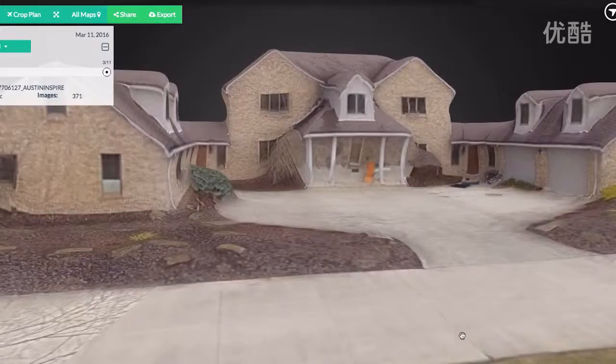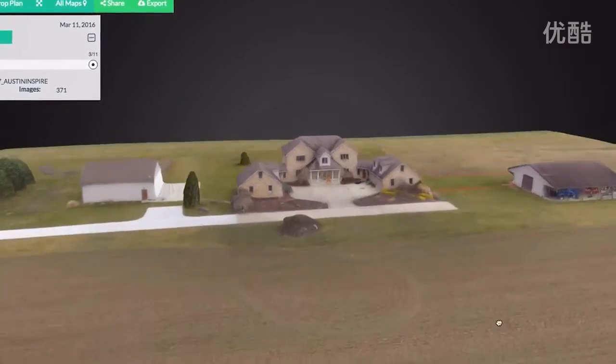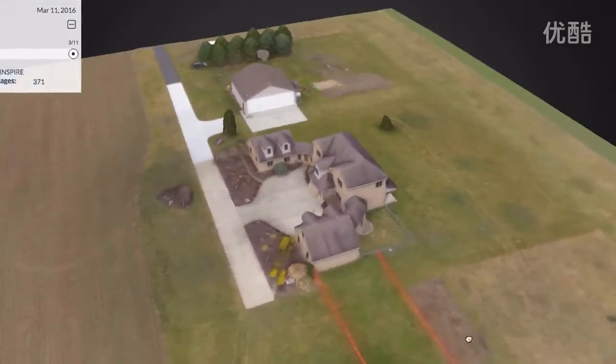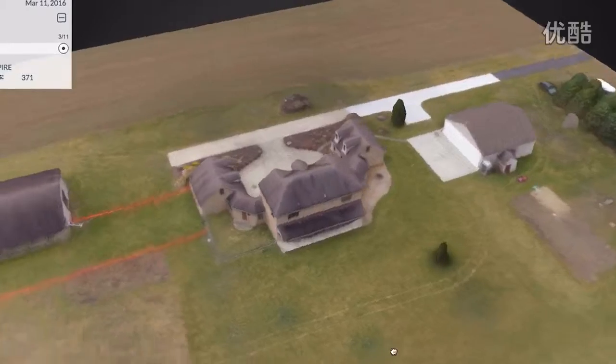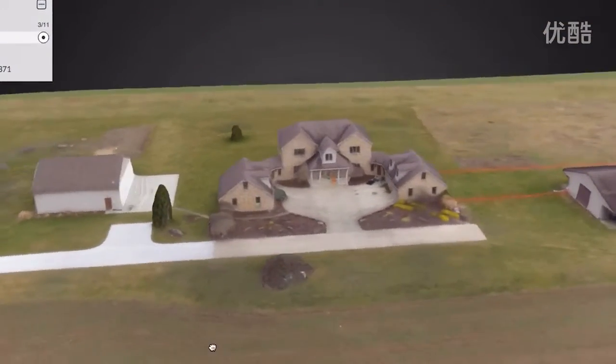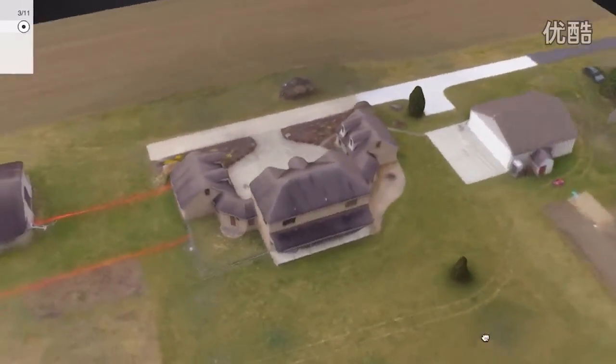Yeah. So the big tip that we got from Drone Deploy support was that for 3D mapping, it is really important to get some more side perspective of any kind of vertical structure that you're trying to film, such as a building or a statue or whatever you're trying to get in a 3D environment. How we did that is we exited out of the Drone Deploy app and pulled up the regular DJI Go app.